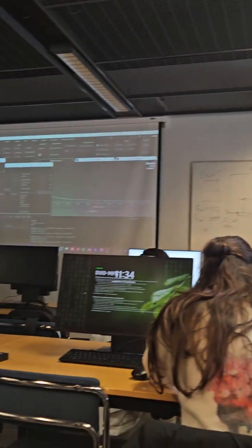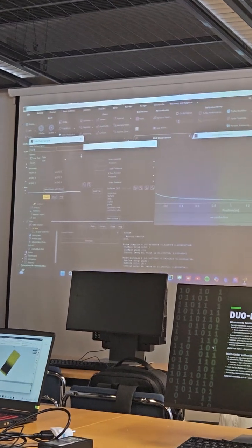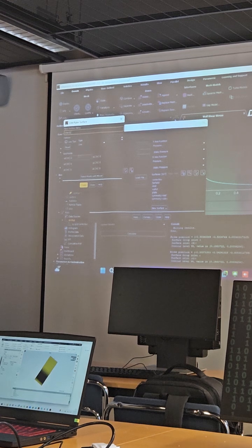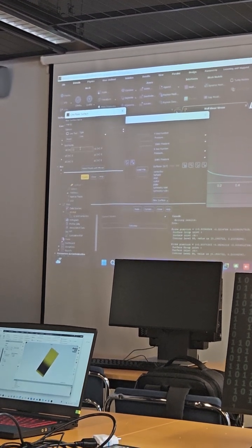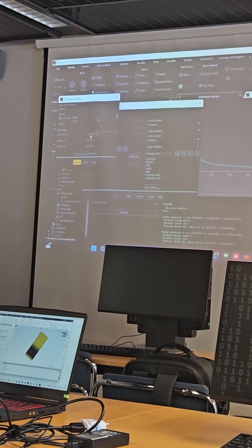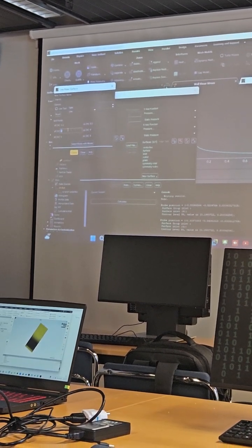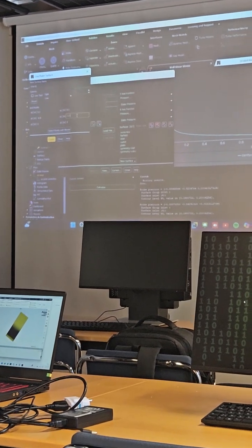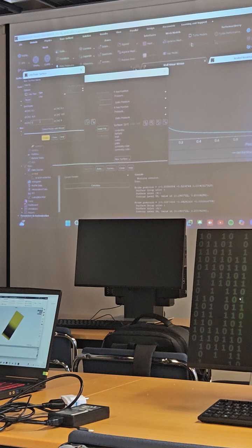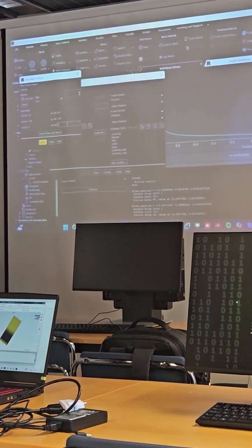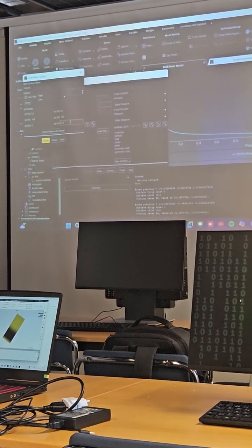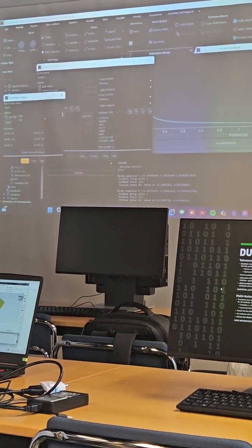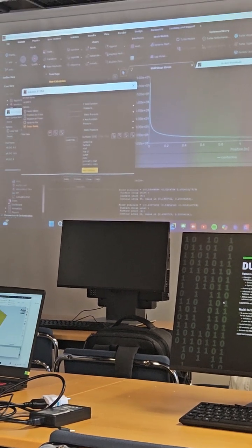For the first point, we can call this line 01. That means this is the line for x equal to 0.1. So we set x0 and x1 equal to 0.1. y0 is minus 0.5, y1 also minus 0.5. z0 is 0, close to the wall, and here we set 0.1 and create. So now we have this line, line 01.